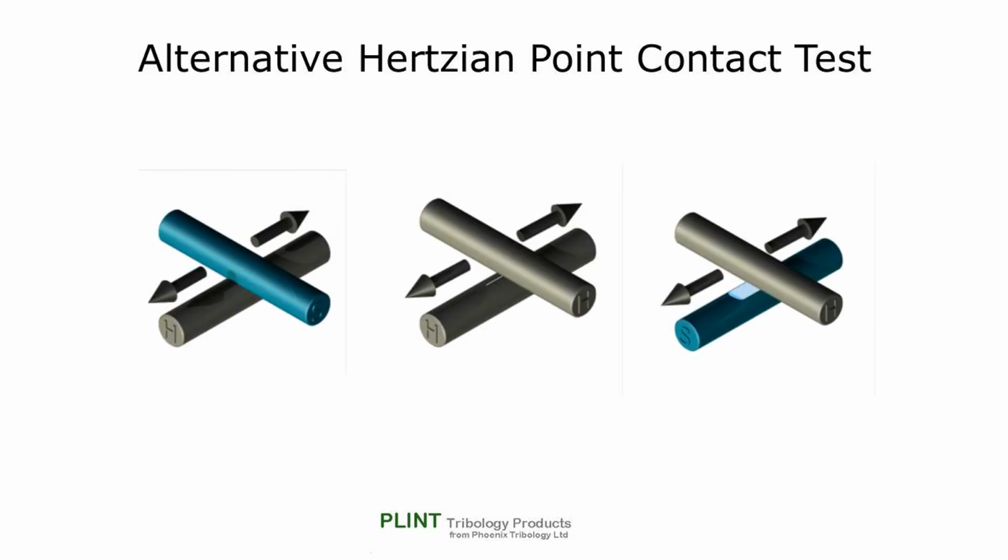I think we can safely say that we've arrived at the point where we can summarize the problems of tribological experiments involving a ball sliding on a flat surface as follows. Such experiments provide poor models for real contacts. It's very difficult to analyze and understand the wear processes in the contact. For lubricated tests, they are relatively insensitive to variations in additive concentration. Measurement of ball wear scars is fraught with difficulty and uncertainty.